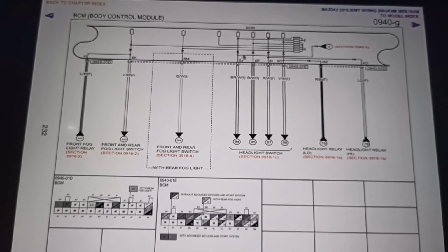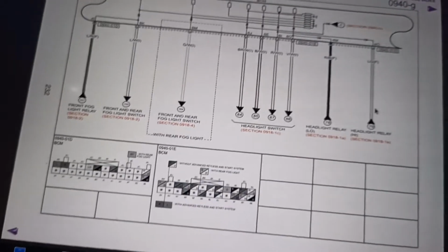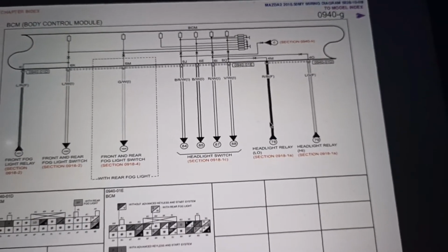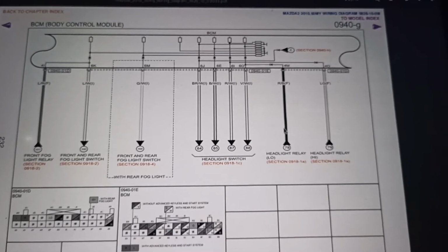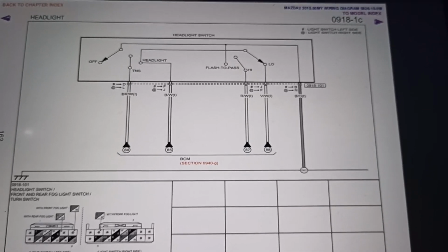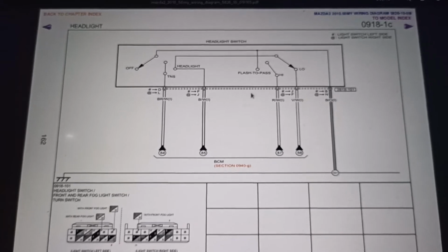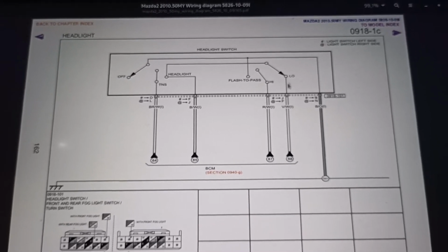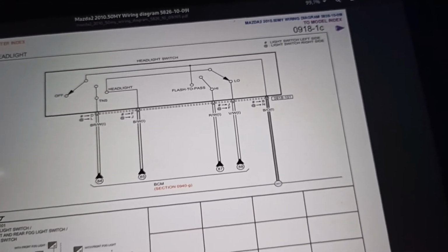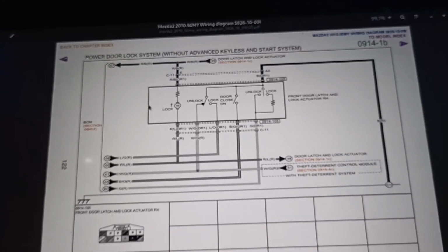As you can see, there is a wire like that, and it's actually going to there, which goes to the relay for the TNS, which controls lots of circuits. This is how we know that brown with white is TNS, there it is, and how we know that violet with white is low beams, there it is. And the last one is the unlock signal.